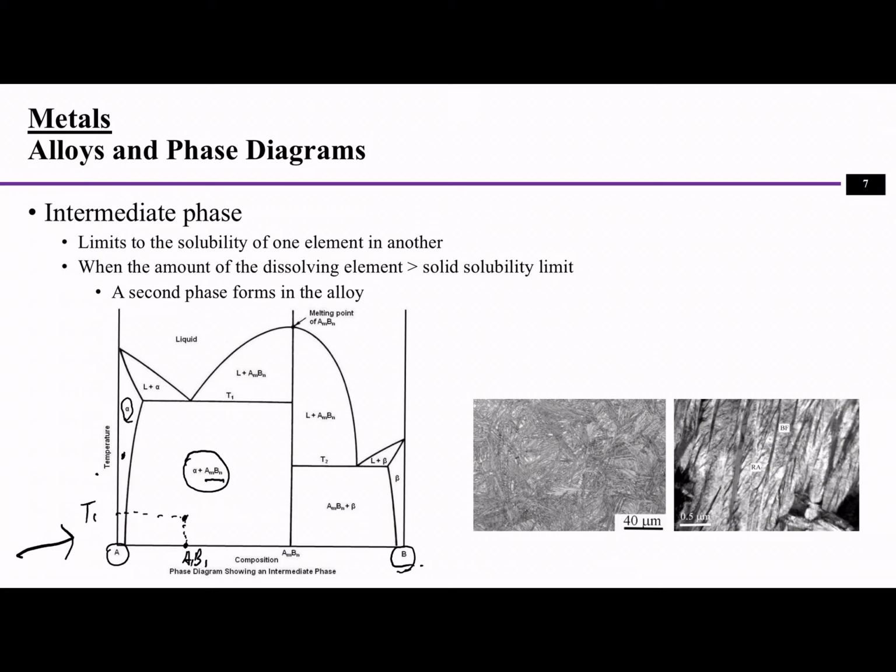If the temperature keeps going up, it will reach a point. So this point is a eutectic point. Eutectic point means it will not go through phases like this and this. See, this phase means it's a mixture of both liquid and solid materials, right? Same with here, it's a mixture of both liquid and solid material.